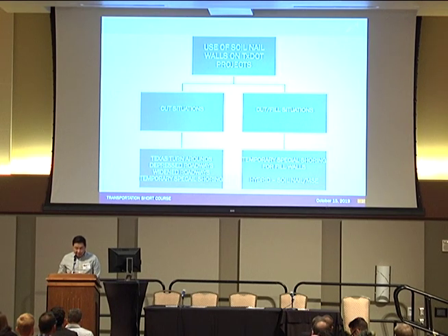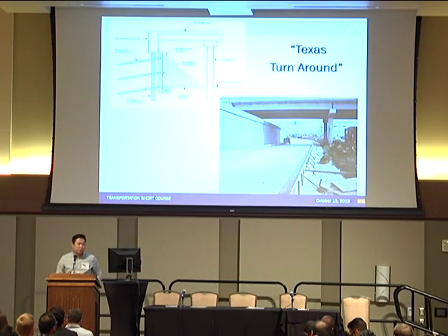Okay, so basically a soil nail retaining wall is used for the cut situation, and can also be used as cut shoring for the fill situation or a cut and fill hybrid condition. This is a very typical application for the soil nail retaining wall. This is a typical cross section for the Texas turnaround. When we add a turnaround at the bridge abutment, we normally cut the header slope, install the soil nails and build the soil nail retaining wall.